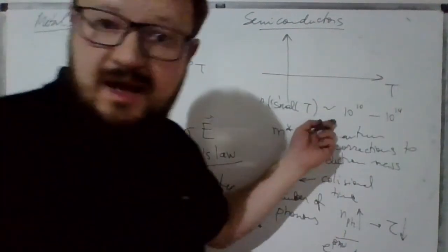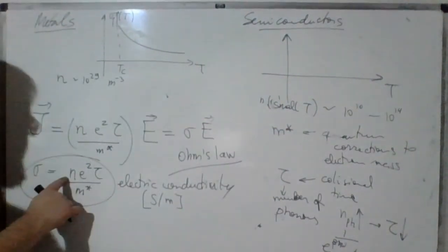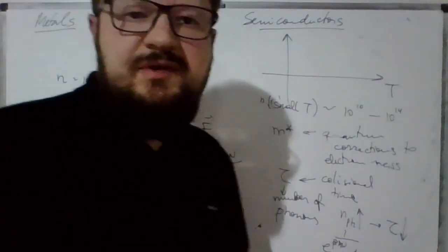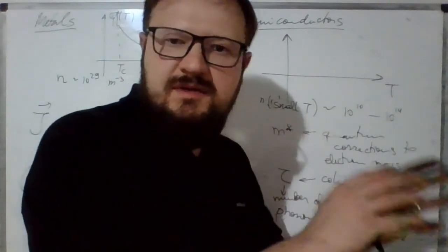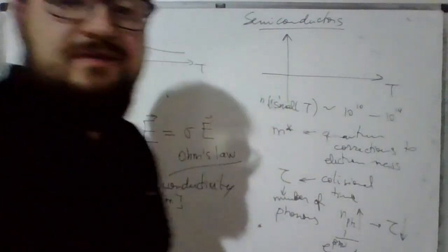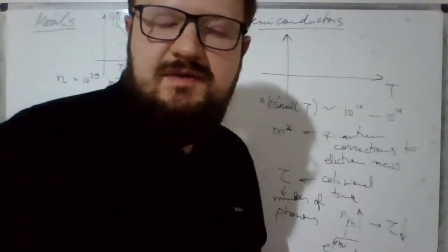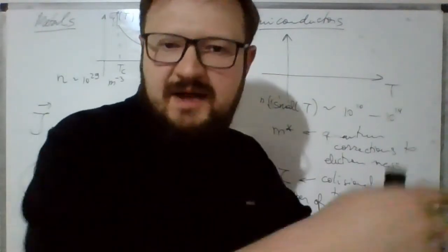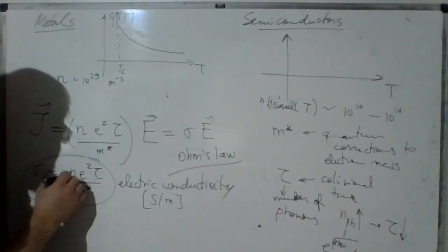So the doping acts on this number, the number of carriers, the total number of particles in your Fermi gas. But temperature, because of the interactions between holes and electrons in the semiconductor, can increase the number of carriers. By thermal activation of your carriers, you can increase this number.